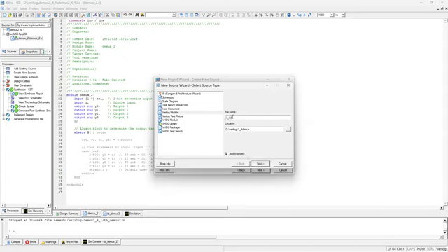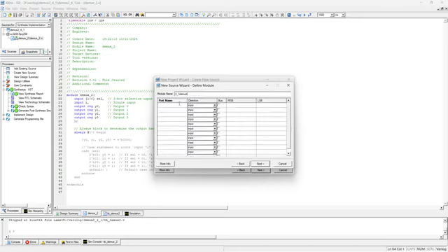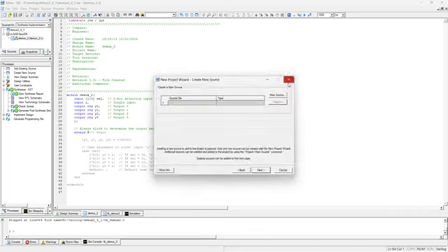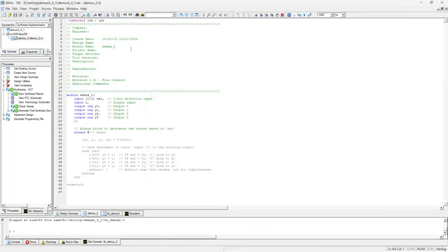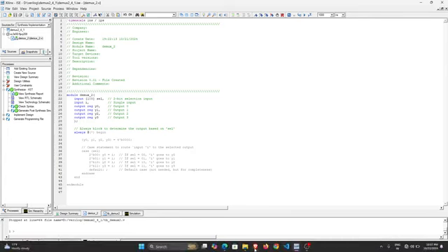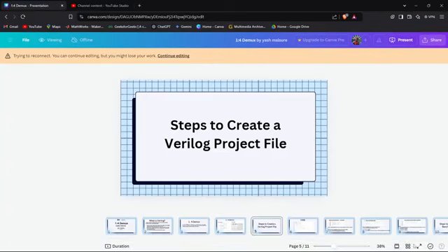You can give any name, but the case should not be uppercase, and there should not be a hyphen in it. Now click next, and here you can give the port names: input line, select line, and outputs Y0, Y1, Y2, Y3. Here I have already created a module of demux 1 is to 4. Now we will go to the PPT.